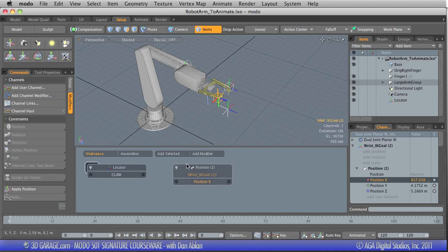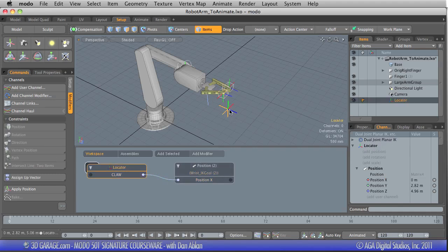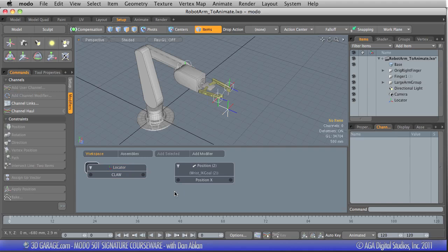All right, so all you need to do is link these two, right? You would think to go like this. Well, not quite, because now you have no control over what it's doing. You saw it move, but it's not really doing anything. So I'm going to select this and just press my backspace key, which is delete. And I want to add a modifier called channel relationship. So channel relationship, I also have previously used right there, and I'll add this relationship.